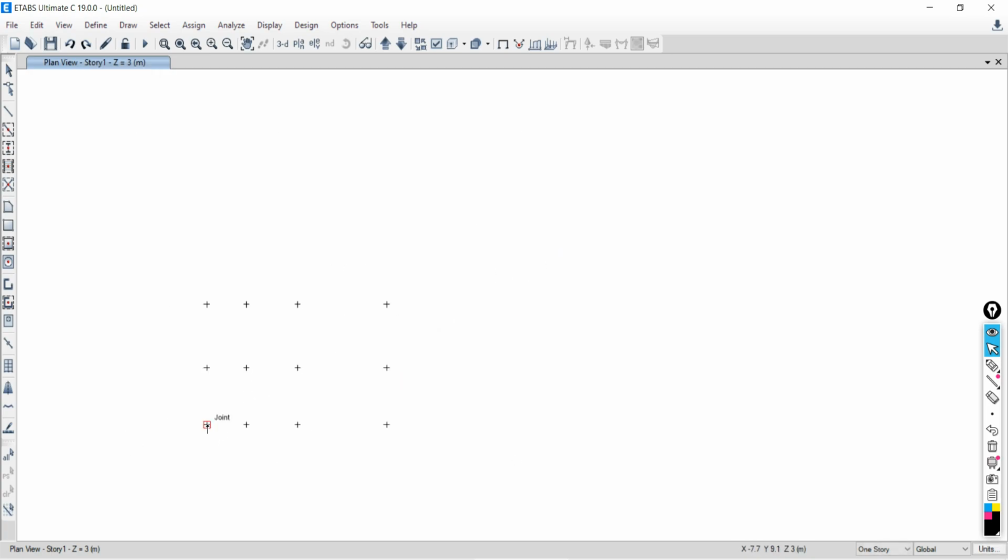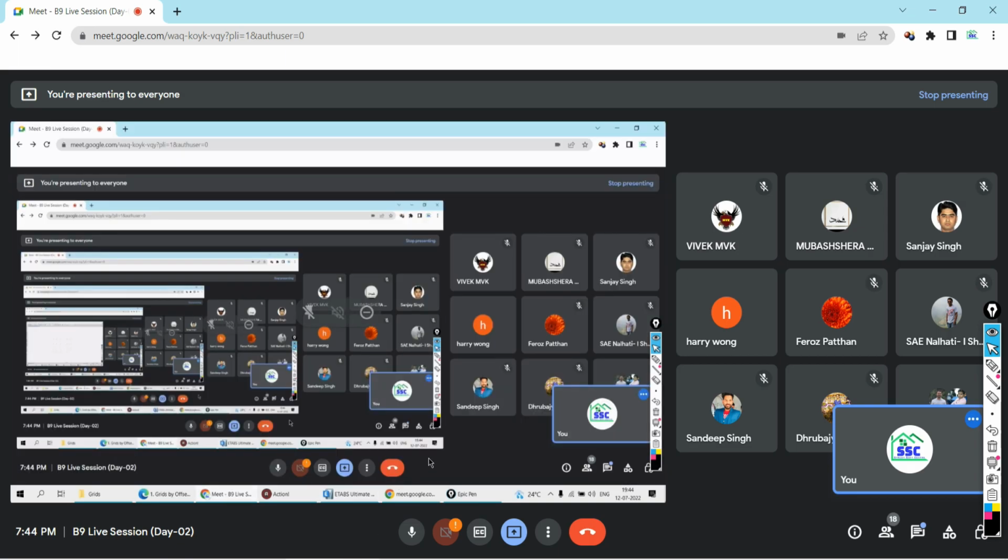You have to move from left to right, click over this point, then from here to here, then from here to here. Now if I don't want the grid labels on the top but on the bottom, move from top to bottom like this, again like this, and again like this. So this is what we call grids. This is the method of preparing the grid lines by the offset point method. Is that all okay? Now you have an option to ask.